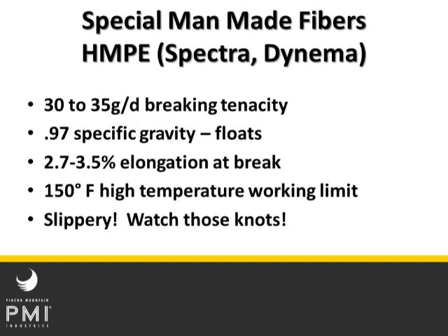The other thing you have to be careful with Spectra and Dyneema as a yarn is that it's very slippery. We did some testing years ago, and you can do a pull test with double fisherman's on a Spectra rope, and the knot will just kind of untie itself, slipping past each other just as it loads up. You need to do triple fisherman's and things like that to get pretty decent strength out of those types of yarns. So you want to be real careful. That's why you'll often see them blended with other yarn fibers to make them easier to sew and to tie knots.